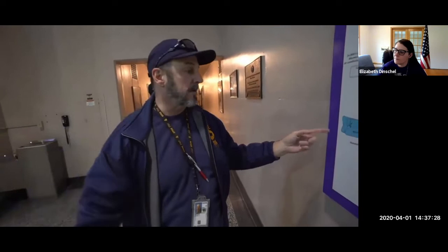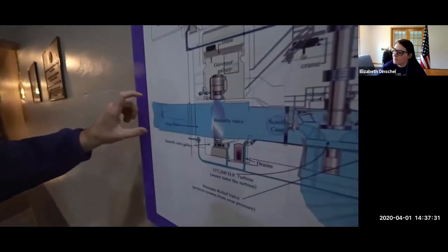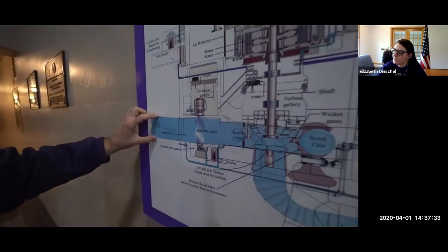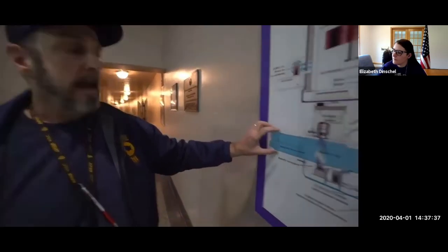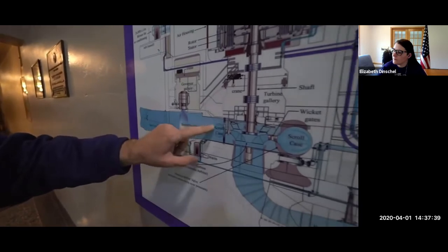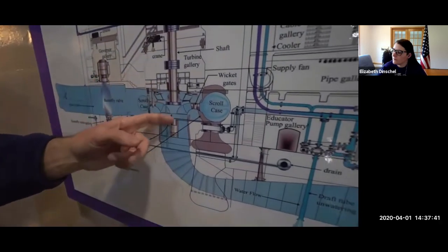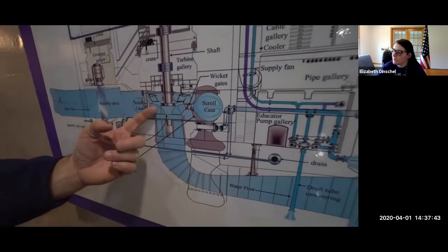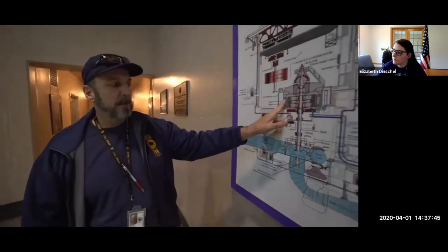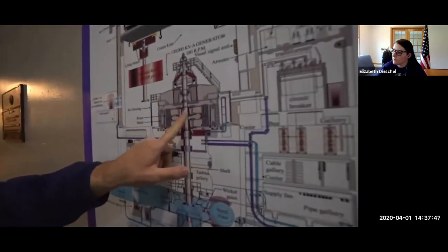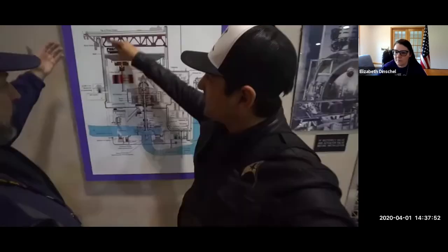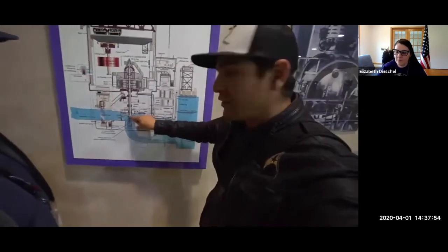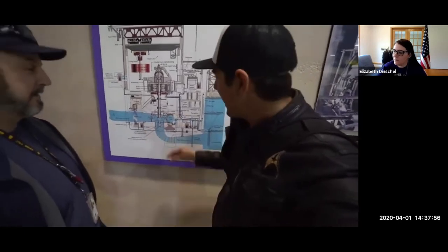Brings the water down around the dam through tunnels, and then it diverges off at each generating unit into a 13-foot pipe called the lateral penstock, and each one of those feeds through a butterfly valve into the scroll case, which turns the turbine, which in turn turns the shaft, which turns the rotor inside the generating unit and creates your electric power. So the water gets sucked in, turns a propeller, sort of, and that's the turbine right